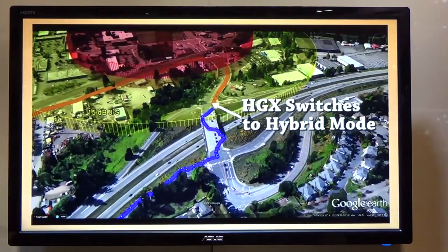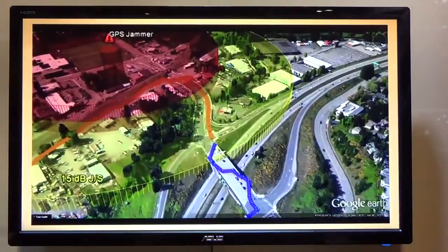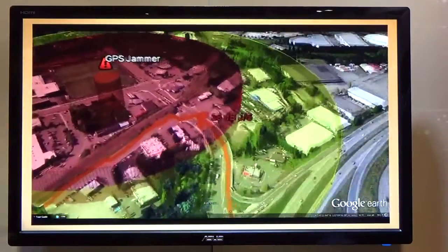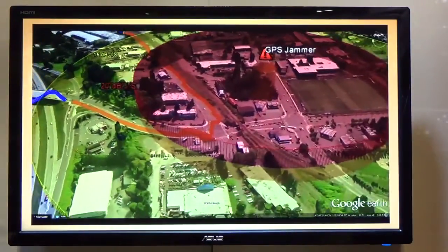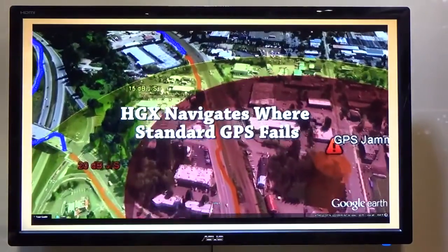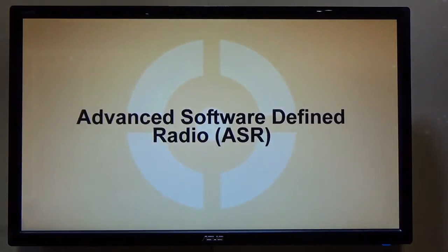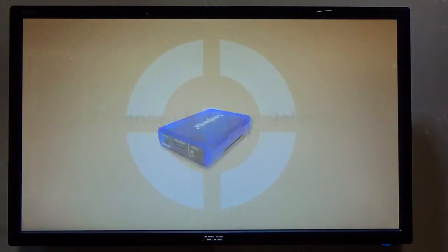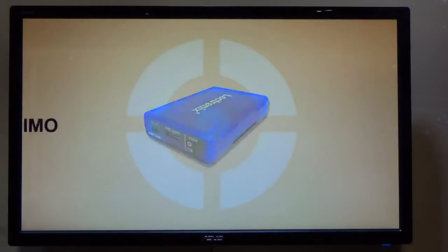As this video is showing, the blue line indicates a traditional GPS receiver dying in about a 15 dB J/S situation, where our advanced algorithms using SCP can pick up and continue to operate well into 20 dB J/S and even higher, all the way up to a 30 dB J/S jamming situation. Once the interference has dropped down to a level that correlation technologies can deal with effectively, we can return back to an ordinary operating state.